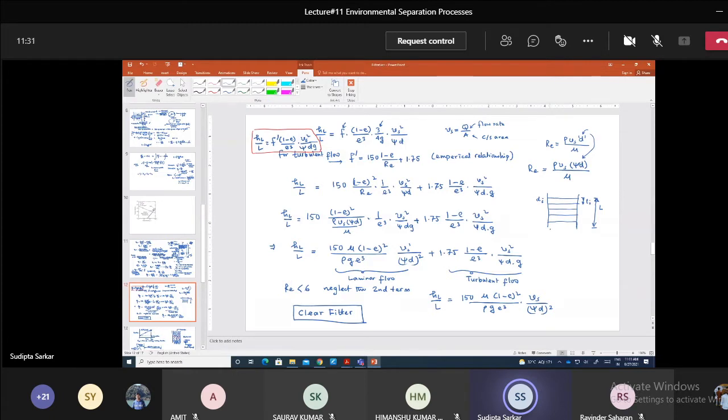For this particular strata, the head loss, let's say HLi. So HLi, look at this formula. HLi equals F dash, 1 minus E by E cubed, and you have Vs square, which is common for everything, and you have psi, which is also the same for the whole bed, and also G is the same for the whole bed.